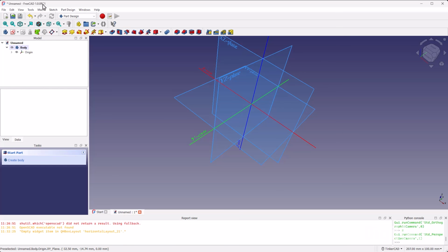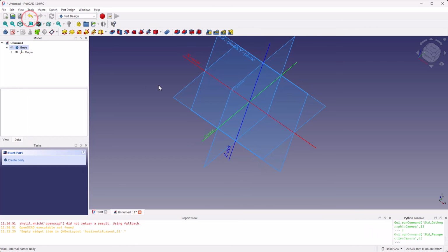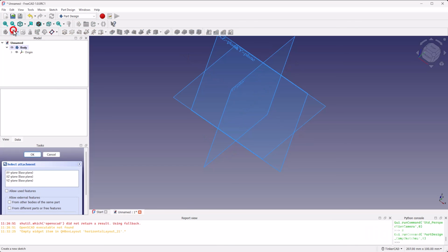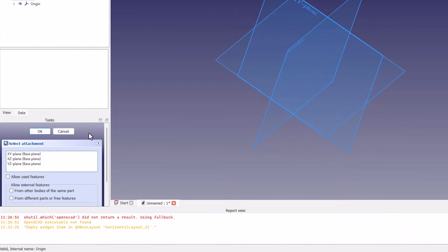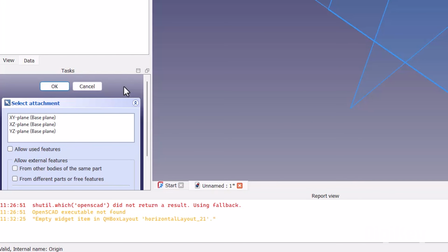when designing parts. The very basic flow of part design is to create a two-dimensional sketch and then create a three-dimensional feature from that sketch. As I showed in the topological naming problem demonstration, we first click on a sketch. Below the tree view pane, you should see the tasks pane change and ask you where to place the sketch.